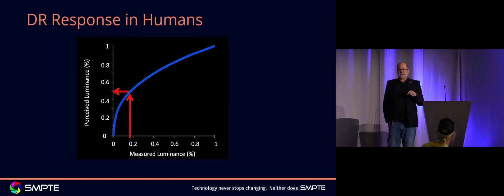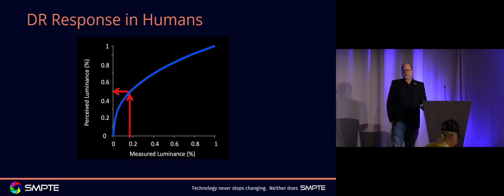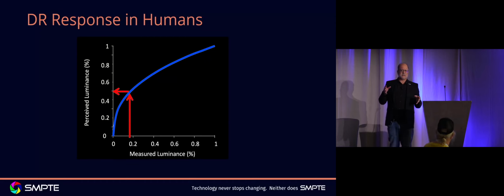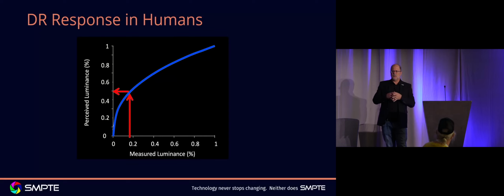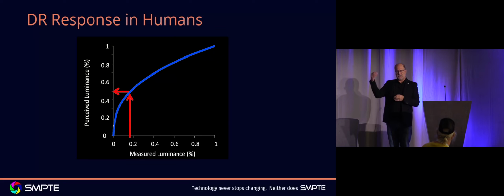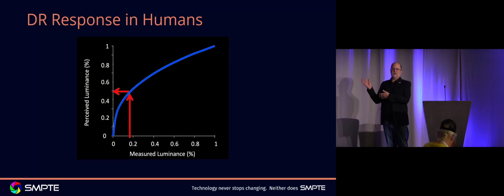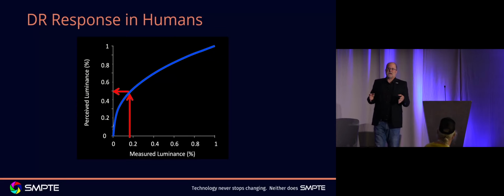For broadcast it's the same. It needs to be flagged when it's transmitted so that your set-top box can recognize the signal and decode it. That creates some challenges when you want to do wide broadcasts of HDR. If I'm in a consumer home, for example, that has an HDR-capable TV and a non-HDR-capable set-top box, it will not work. Or I have an HDR-capable set-top box and an HDR-capable TV, but I've installed an amplifier in between for my audio. It's an HDMI 1.4 amplifier. It will strip the metadata. You will lose it, and you will not be able to see it. So there are significant challenges to